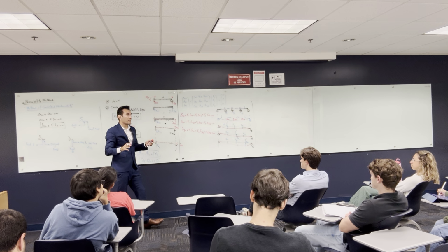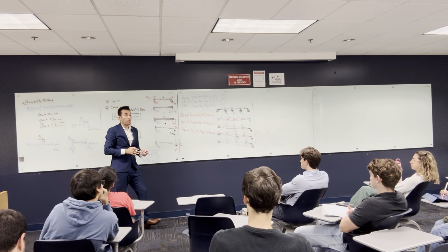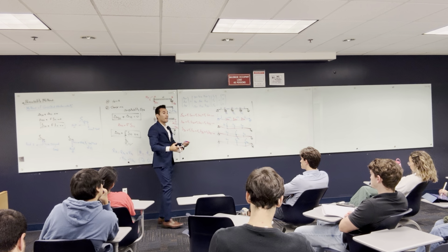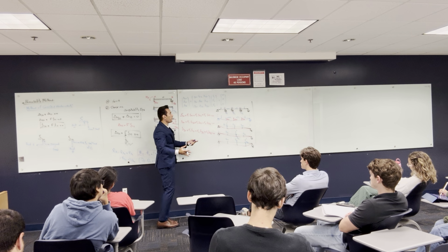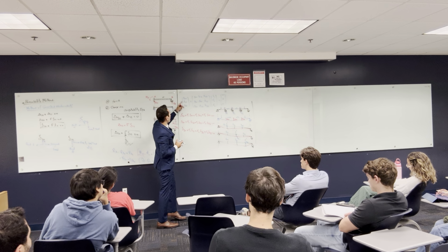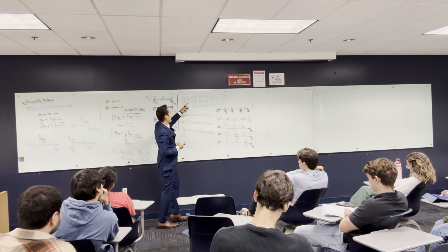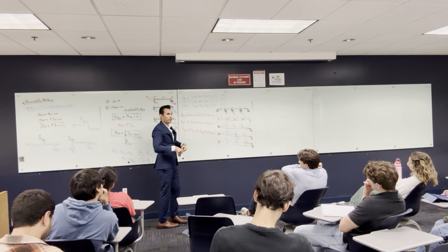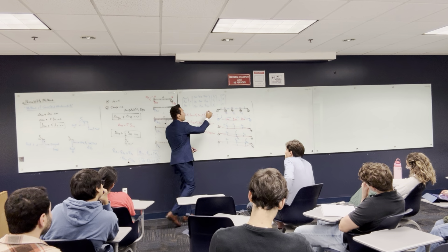That's why usually this method is very good up to 3 redundants. If it's more than 3 redundants, it's going to be more difficult to solve unless you have a calculator that can solve 4 or 5 equations. Because basically, all we are going to do is find the values of these deltas, build this matrix, and give the numbers to the calculator.